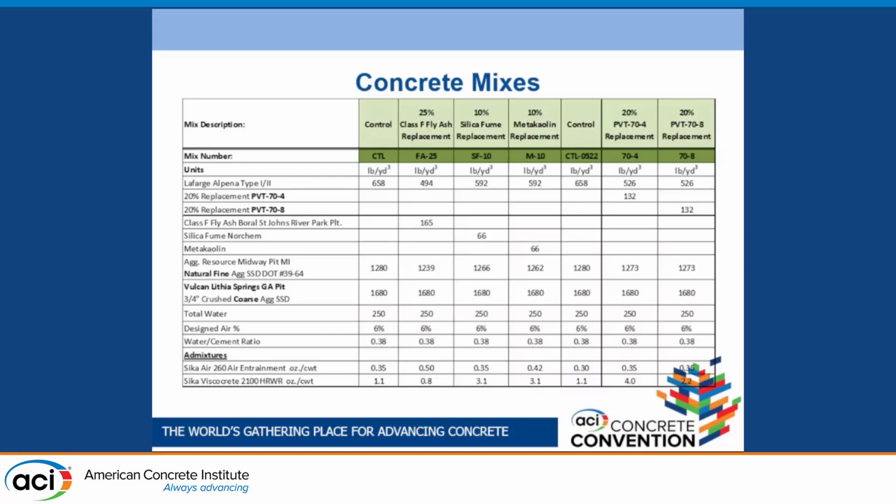You can see that you get a cement reduction, obviously, when you add all these materials to it. So that's very good from that point of view. And you can see just how much reduced. And these are relatively low cement contents compared to what often can end up in high performance concretes. And we go through the various mixes.